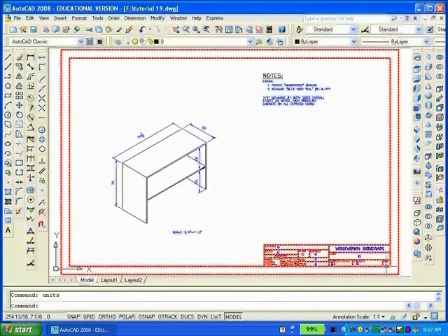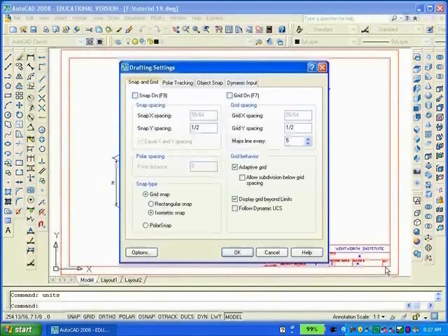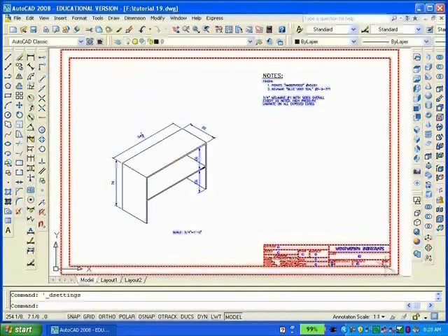Next, on the Tools menu, click on Drafting Settings and select the Isometric Snap. The isometric snap makes it possible to toggle the crosshairs using the F5 key. That key allows us to draw on different planes, as you will soon see. Now I'll move into a split screen to make the drawing.